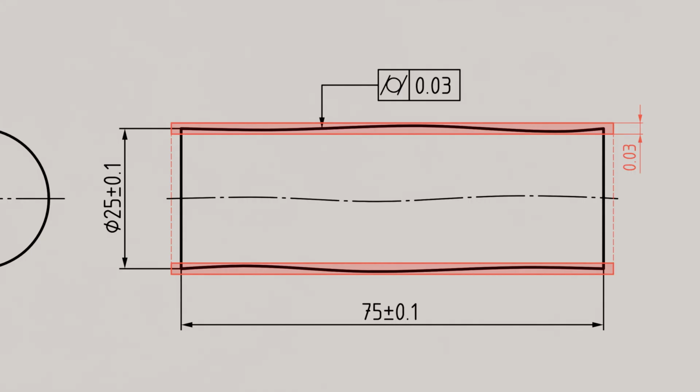As can be seen from the two-dimensional drawing, cylindricity not only limits the deviation of the geometry from the ideal cylindrical form, but also the straightness of the cylindrical surface. Essentially, in the shown two-dimensional representation, we are dealing with two parallel lines within which the generatrix of the shaft surface must lie. This corresponds exactly to the definition of straightness. The same applies to axiality, which means the straightness of the shaft axis. This is also indirectly controlled by the cylindricity tolerance.